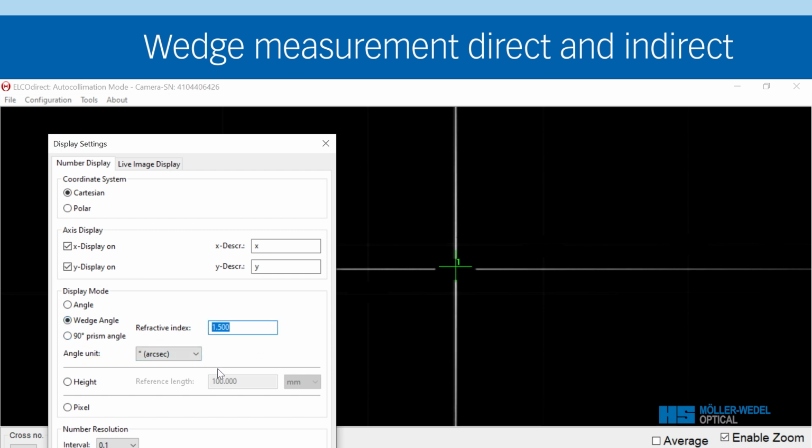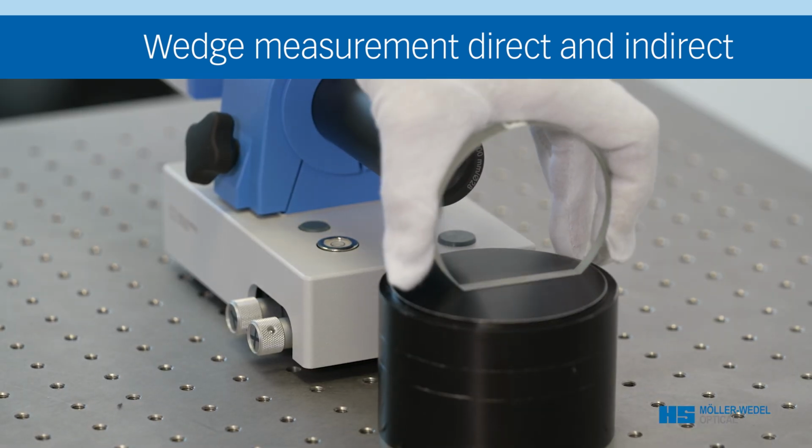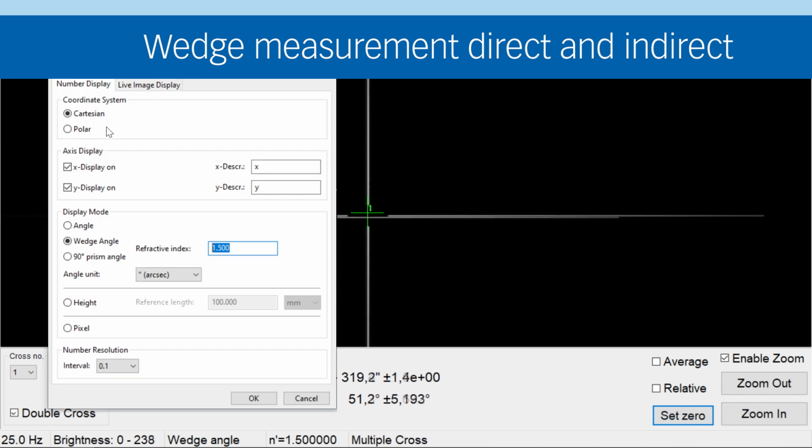It is important to specify the exact refractive index of the substrate to be measured. The wedge to be measured is placed in front of the Elcomat Direct N, and the software determines the X and Y angle offset of the front and back surfaces. The system can output the wedge angle either in polar coordinates, i.e. as the total wedge angle with the associated rotation angle phi, or in Cartesian coordinates, i.e. as the wedge angle in the X and Y directions.